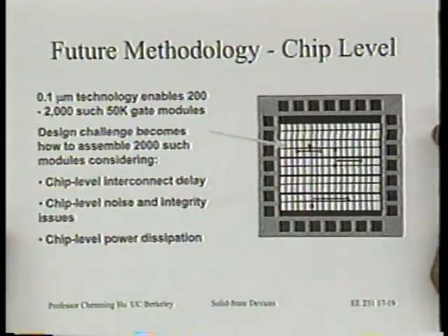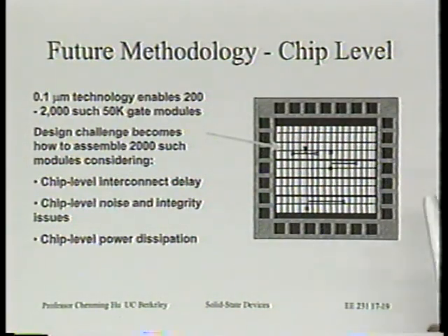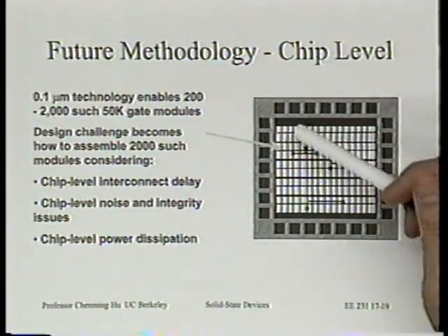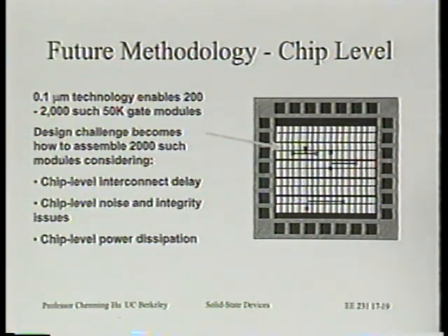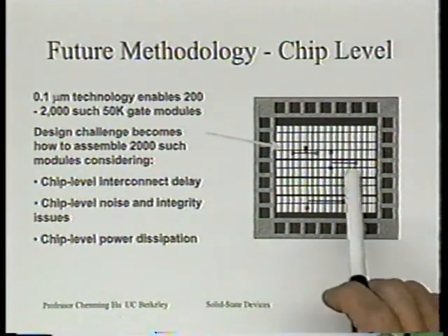So therefore, one can simplify the interconnect problem in the following way. Visualize that the chip is going to be made of many of these circuit blocks. Within a block, it turns out the old way of designing circuits is not too bad. That is, we don't have to totally change the device-centric view or style of circuit design. Once you've designed these blocks, these IPs, then there needs to be much more care in the place and route to connect these blocks.